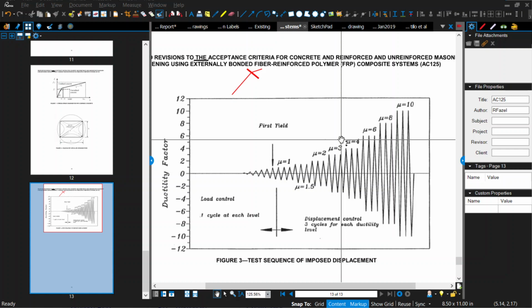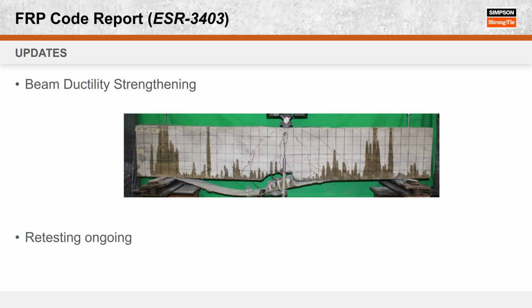But for fatigue loading, that would be like you have a bridge with a truck going over it over and over again, and so it would be about the same load. And a million times. Yeah, and the load amount for fatigue is usually like the service load. So if you run a fatigue test, you're going to load a beam up to its service load, or maybe like 110% of the service load, like a million times. Fatigue tests can have millions of cycles in them, so that's the difference.